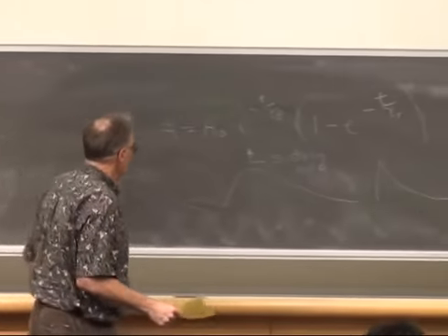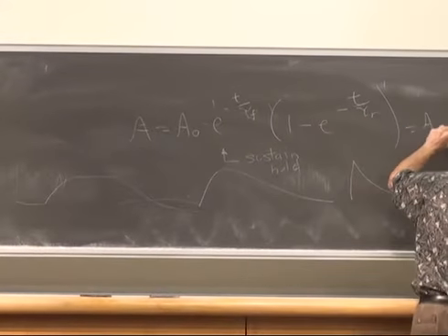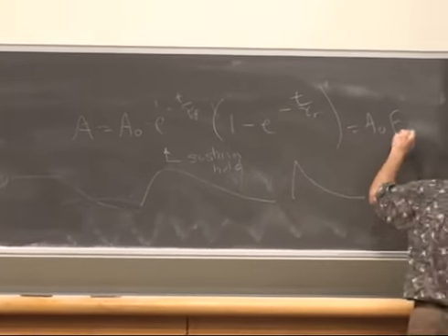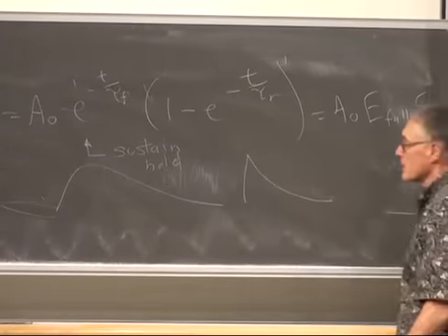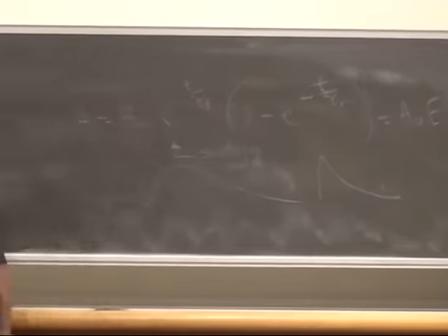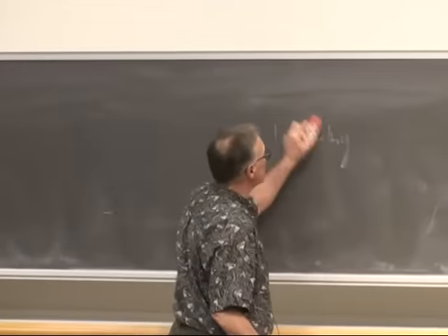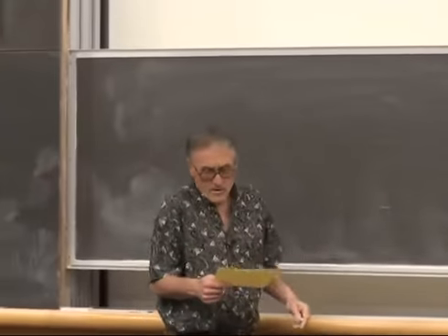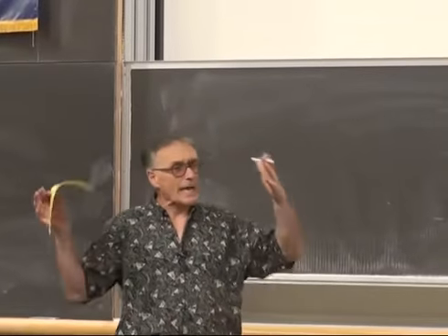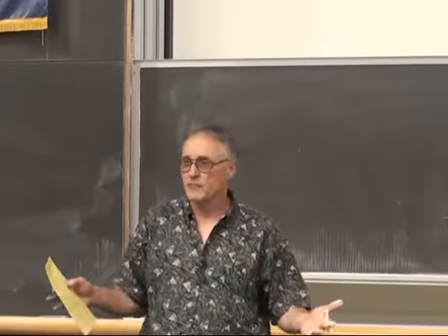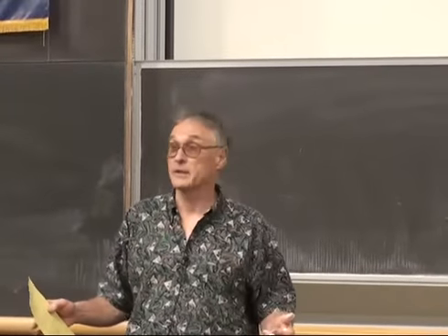So let's abstract this slightly: A naught is equal to envelope fall times envelope rise. And then think about how to calculate the rise and fall envelopes separately. And they're first order systems. So we could have a gigantic table of exponentials. You can't afford to do exponentials in real time because it's 7 or 8 multiplies to calculate an exponential.